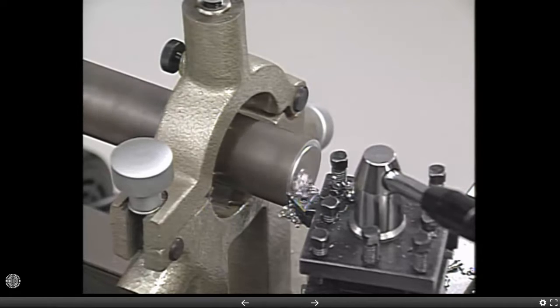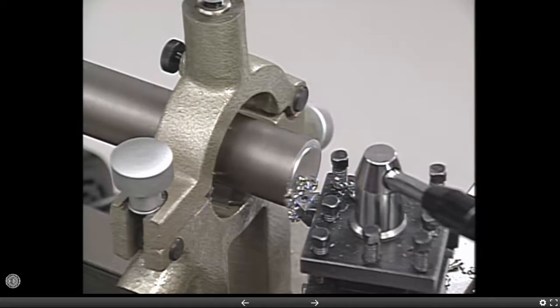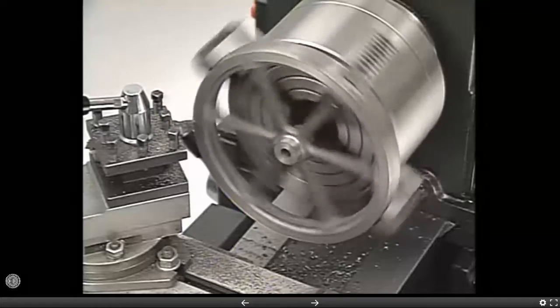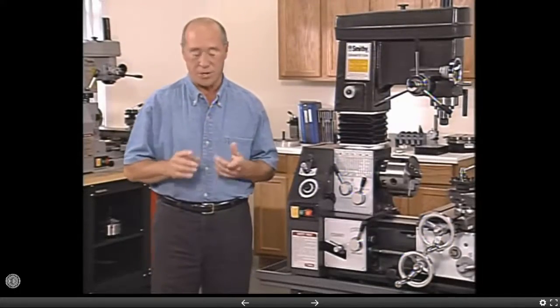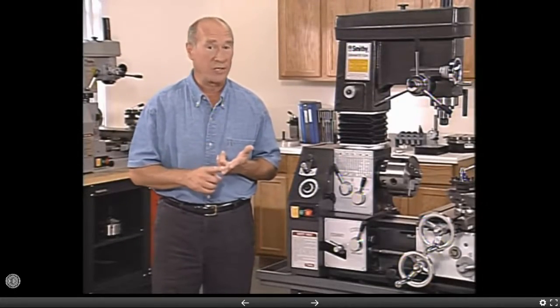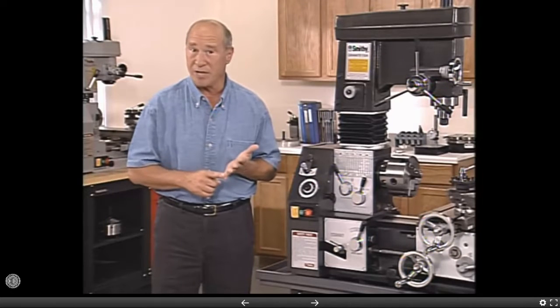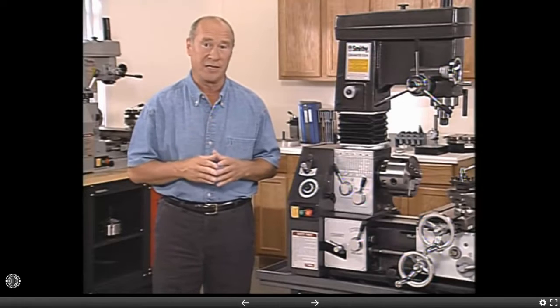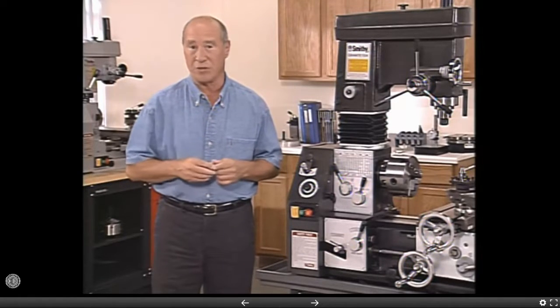Third, the workpiece, or in other words, the metal you intend to cut, must be mounted securely on the machine, able to resist the force of the cutting tools. And fourth, the correct cutting speed should be used. These 4 points, tool sharpness, tool holding, work holding, and speed of the cut, all have a direct effect on the ability of the machine to work efficiently, and in the long run, an effect on the quality of your work.